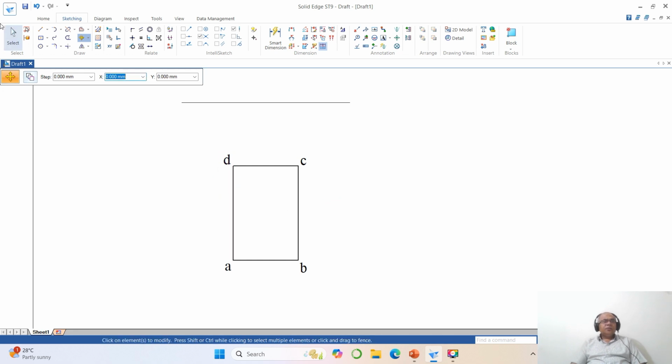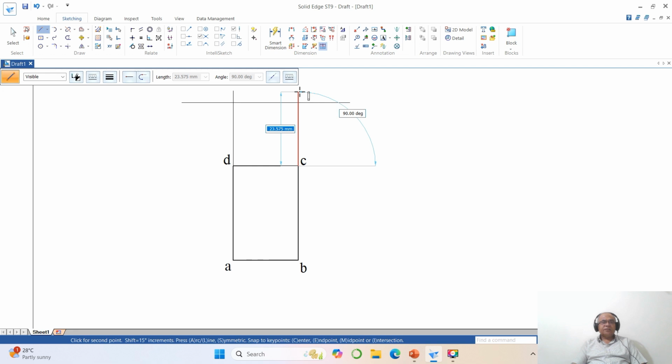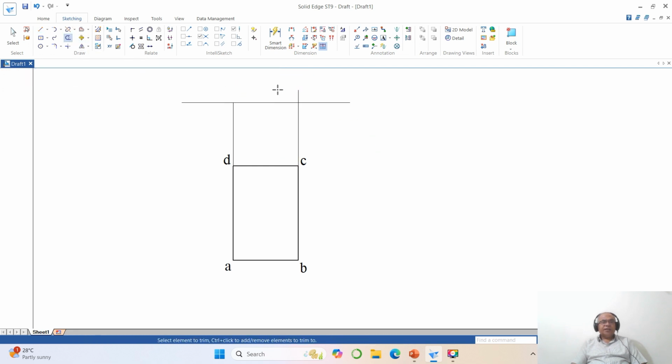Okay. Now we go for the Line command. Draw a line from the intersection point of this, a vertical projector to the XY line. Similarly from here, draw a vertical projector to the XY line. Then go to Trim these two lines, and here also trim this. Now you go to Sketch, select this line and make that line 0.5.